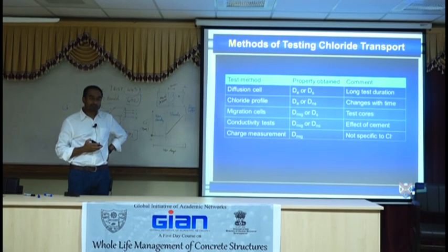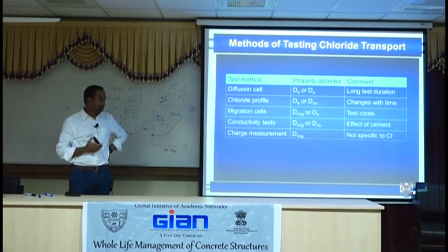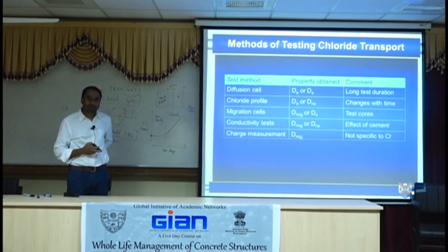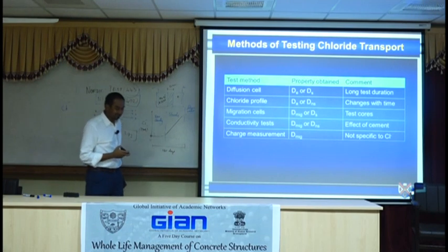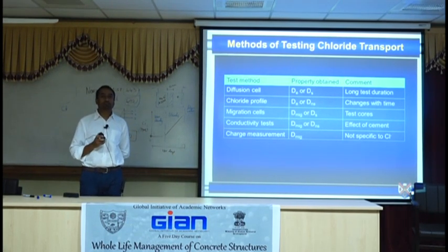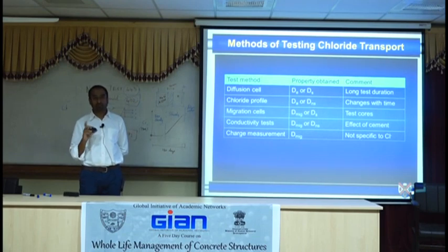Same for concentration 3.5%. So the tests are the same. They have drilled it and they are saying that it has not penetrated. They both are right. Then how should we judge that our concrete is good? You should judge based on the performance. They did say the penetration is low on the second M40, and that's suitable. No matter how you look at it, that's suitable.